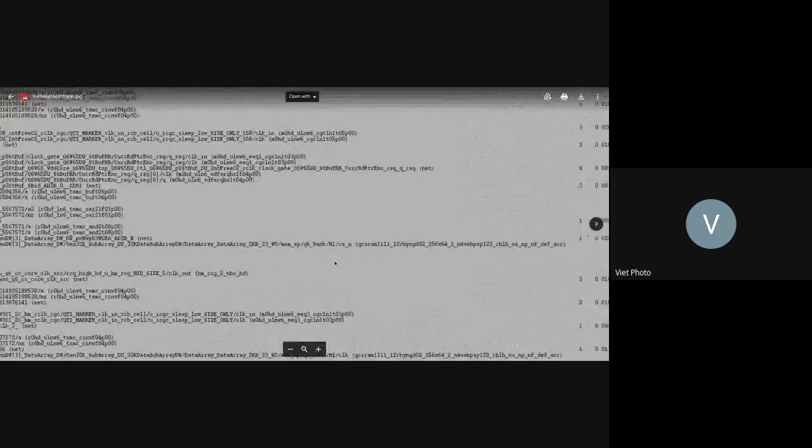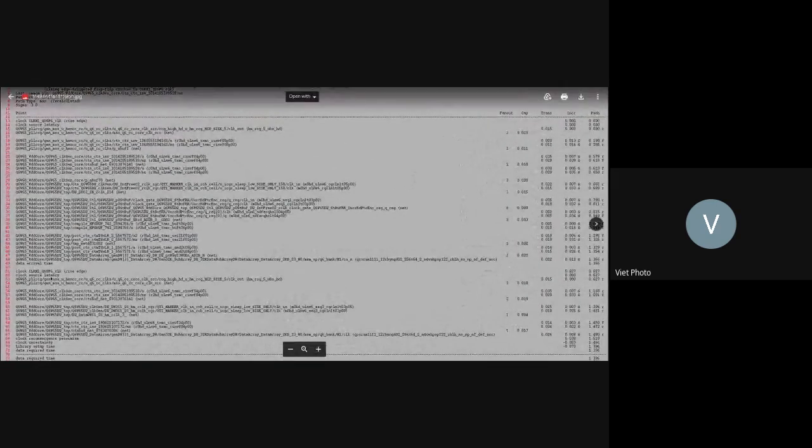Now we go to this one. This one is the capture clock. For this capture clock, you see from the beginning it is also 0. But because it takes one period, the period is 627 picosecond, right? So we add it in here so that it checks. The clock source latency is 0 here, but when it checks the arrival time, like a requirement, it has to add the period.